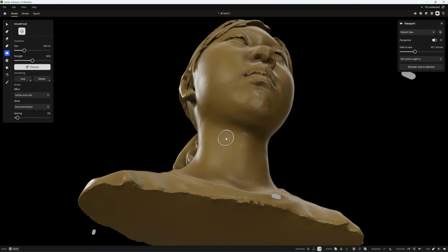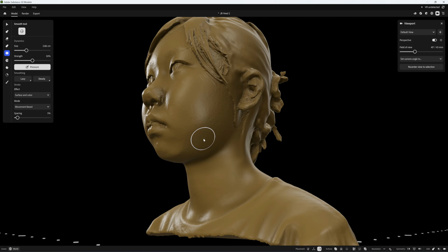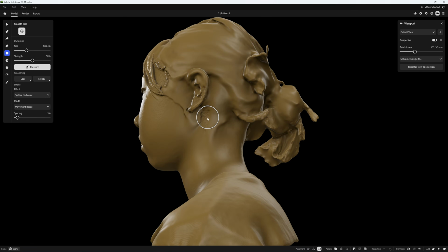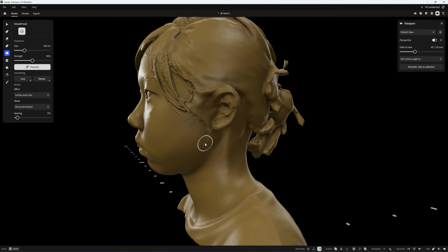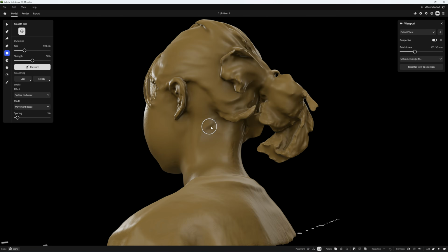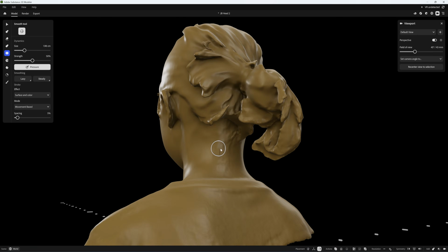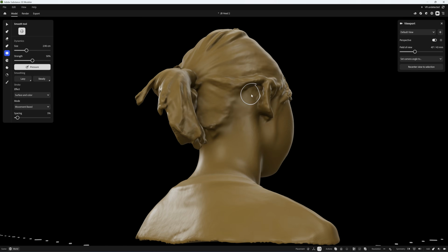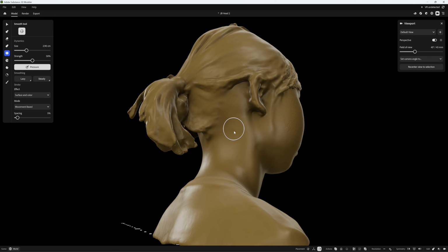The Creality Scan software, the new beta version, its default value for the exposure is 100% brightness, so I didn't change the exposure. I try to remove defects by smoothing out, and you can get almost everything done with the smoothing tools.